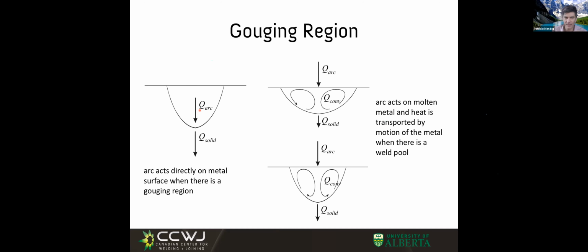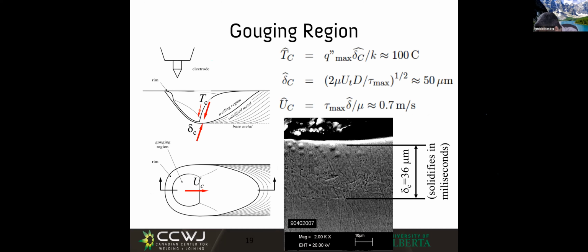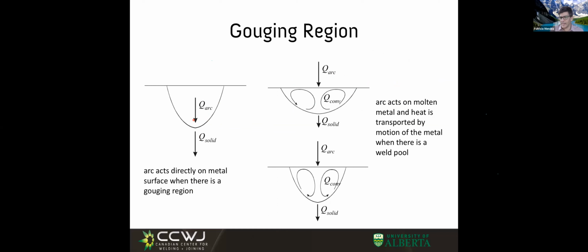Question to you. In this penetration mechanism, and this might be one of the last things we discuss, I would like to hear a word. Do you think sulfur, do you think surface active elements play a role? Do you think high sulfur and low sulfur would give us different penetrations? I'd like to hear. Well, aha. Well, thank you. Somebody ventured the guess.